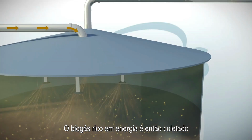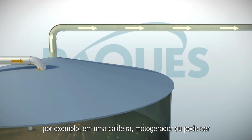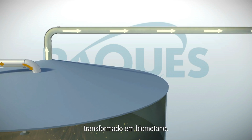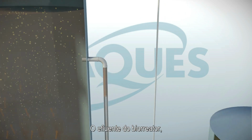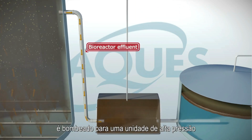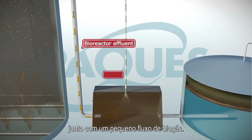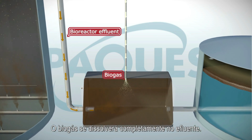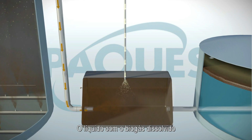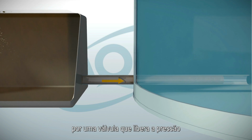The energy-rich biogas is then collected in the headspace, leaves the bioreactor, and can be used, for example, in a CHP, boiler, or can be upgraded into natural gas. The effluent of the bioreactor that contains biomass and purified wastewater is pumped into a high-pressure unit, together with a small flow of biogas. The biogas will dissolve completely in the effluent. The liquid with the dissolved biogas leaves the high-pressure unit and passes a valve that releases the pressure in the liquid.